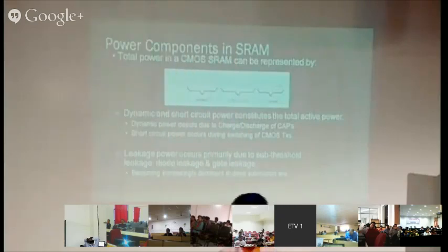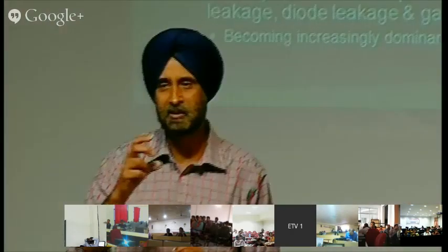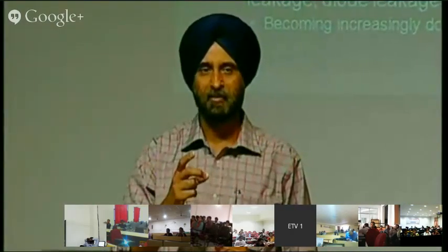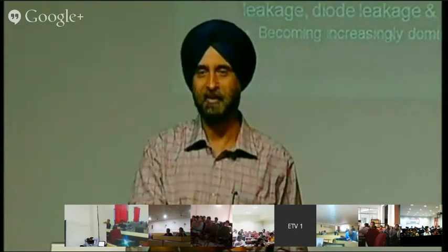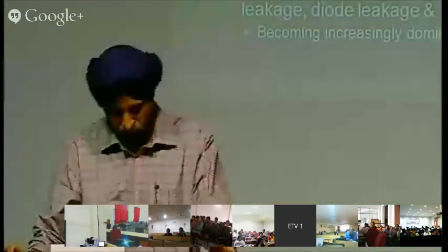That is known as the subthreshold current, below threshold, sub-threshold. It may be in nanoamps, less than nanoamps, picoamps, but say it is 1 nanoamp. But in a chip, if there are 1 million transistors, you multiply 1 million into 1 nanoamp. So how much current does it become? When the transistor sizes are reducing, the number of transistors on a chip is also increasing. So this power also becomes more.